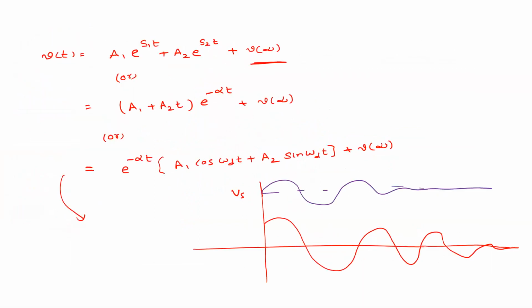Okay. So this is the simple step response of a series RLC circuit. Similarly, this is about voltages, right? So these things can be generalized. For example, if you want a current i(t), how will you write the current response? This i(t) can be represented as i transient plus i steady state part.